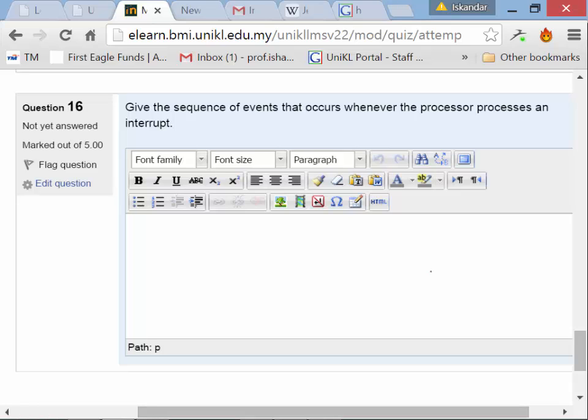It then pushes onto the stack the return address so it knows where to come back to, and then it loads into the program counter the address that's listed for that particular interrupt in the interrupt vector table in order to execute the interrupt service routine. So it goes to the interrupt vector table and gets the address of the interrupt service routine. That question was earlier in the test. So a lot of these questions get repeated. So it executes the interrupt service routine.